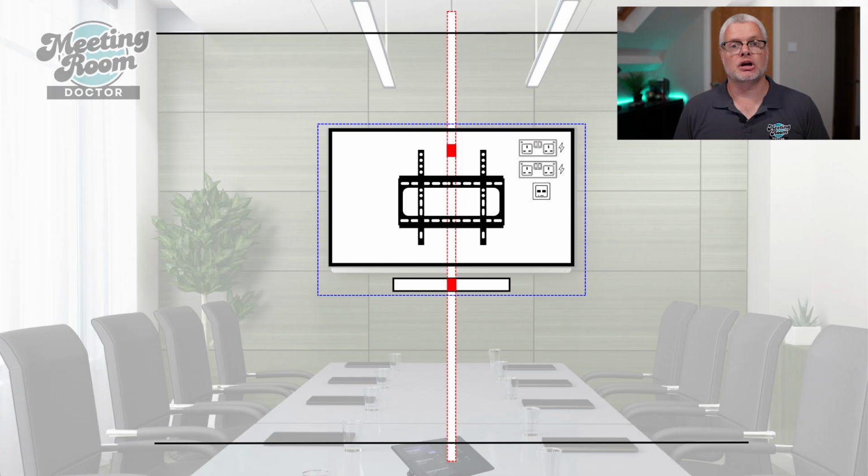What you see in this image are the enablement items that sit behind the visible audiovisual equipment. So you'll notice an area that's been marked out for wall reinforcement. This is to ensure that the wall is strong enough to hold the screen and the video conferencing equipment. We've got marked out cable routes, which means that you can route cables to wherever they're needed. And you've got a display mount that's suitably sized for the screen that's going on the wall, and also the installation environment as well. And then also on that image, we've got power and data.